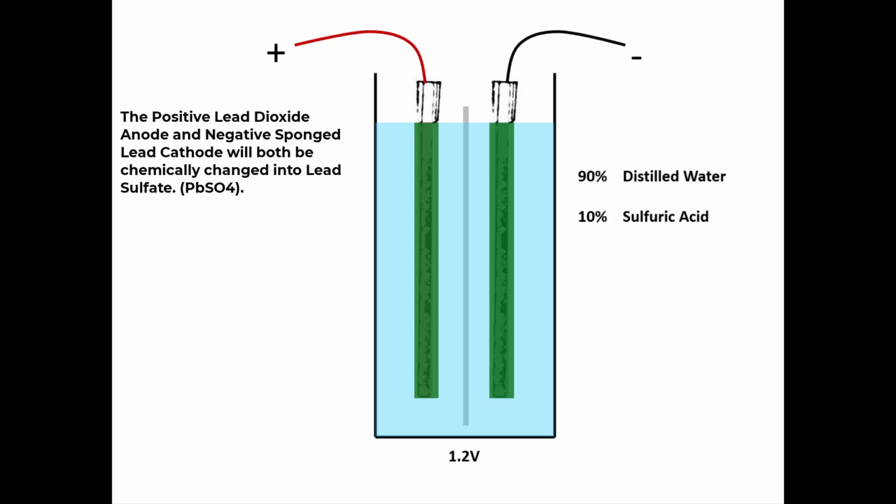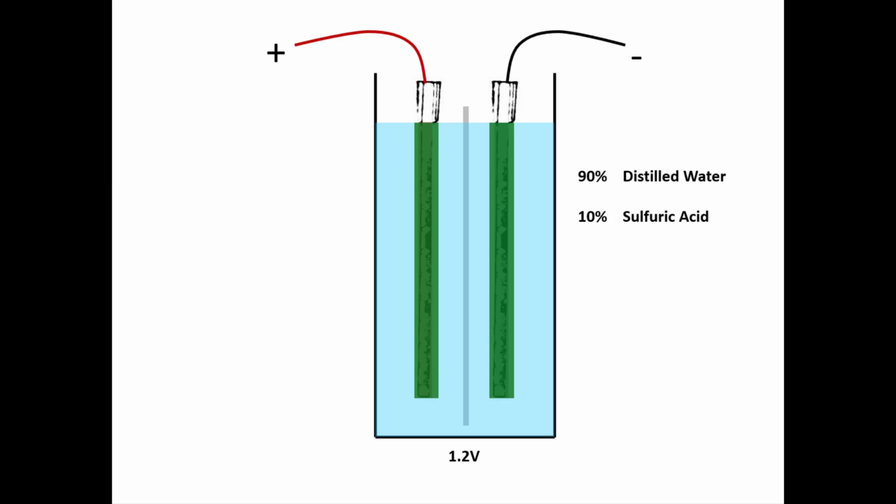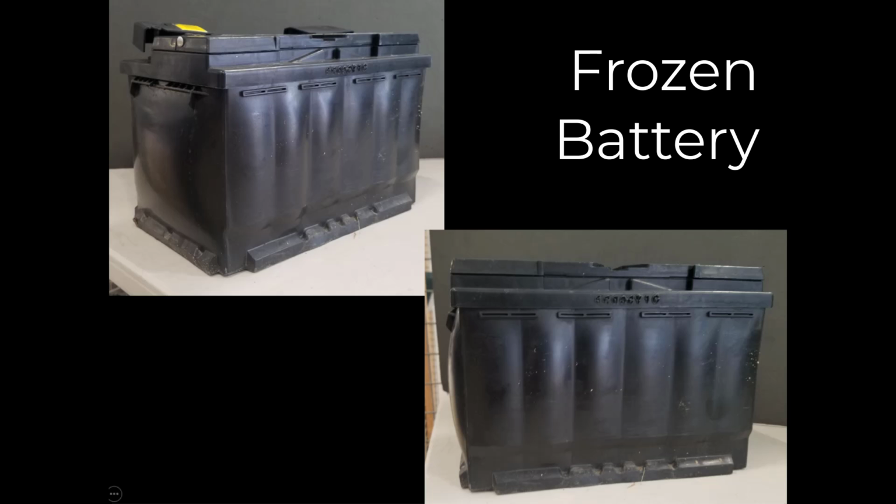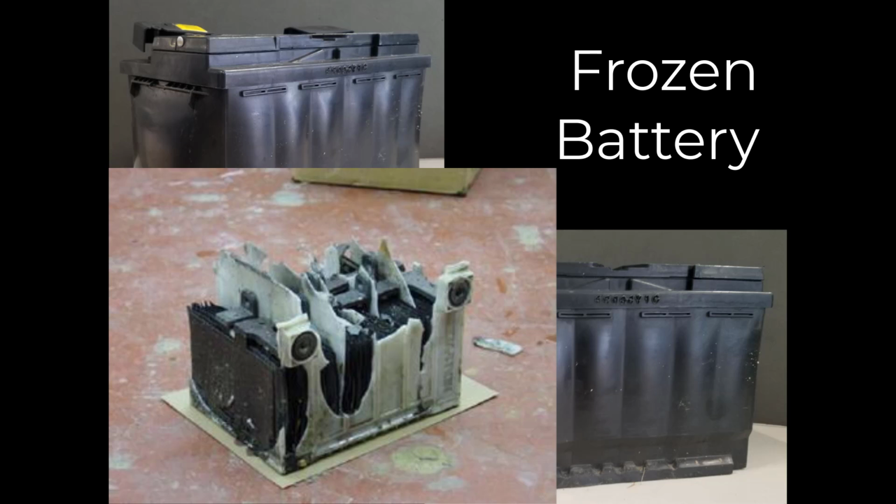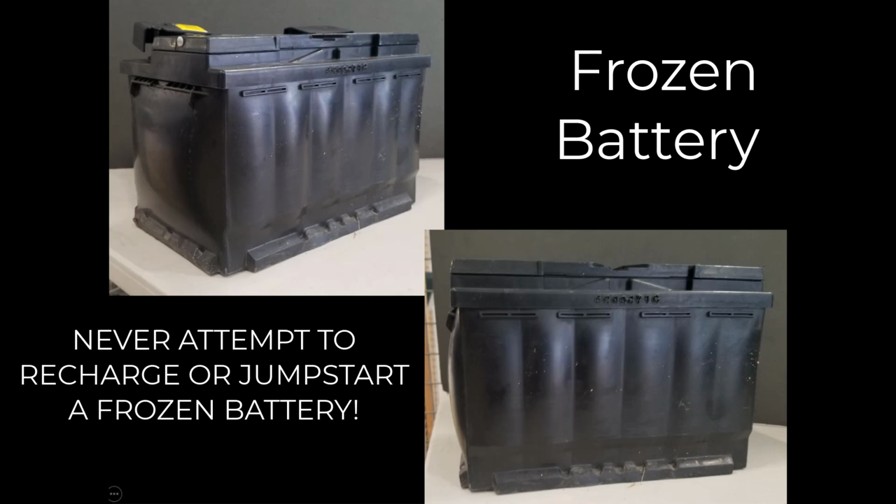A couple of things to talk about with this transfer. Because we have more water and less acid, the water is more susceptible to temperature. If this battery were to get really, really cold, well below freezing, the water could freeze, and if it freezes, it will expand. This expansion can damage the case and warp the plates. It also inadvertently creates little pockets of hydrogen, which create a bigger hazard of a potential explosion. So if you ever suspect a battery is frozen because it's swollen, you should never attempt to recharge it or to jumpstart it. The correct course of action would be to replace it.